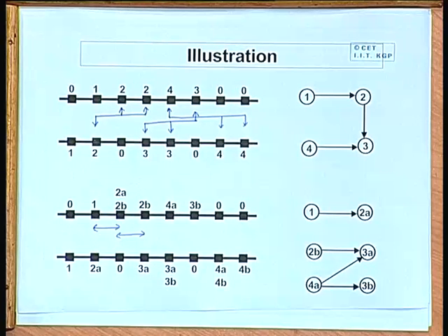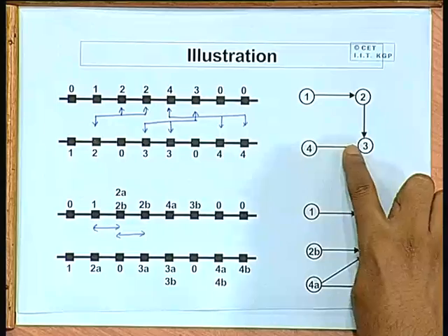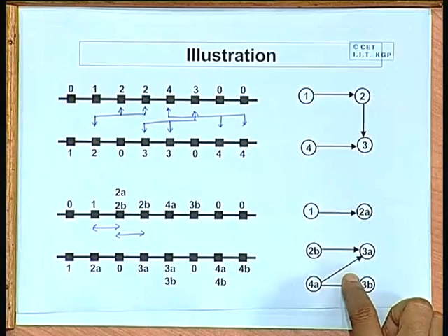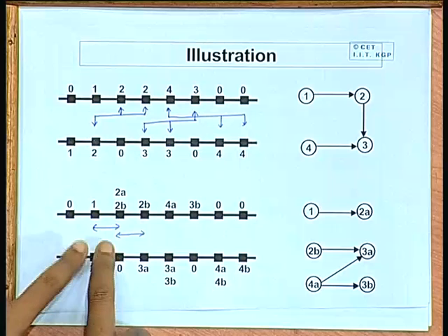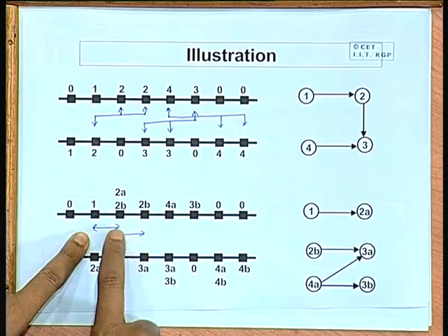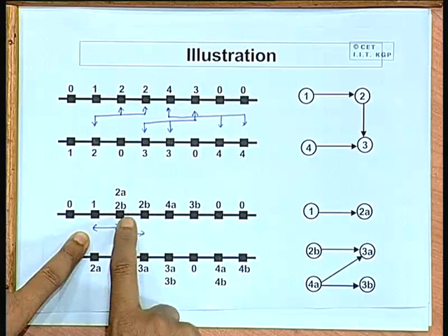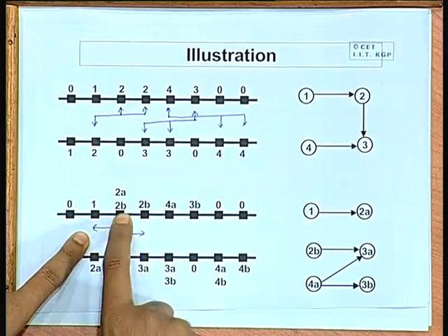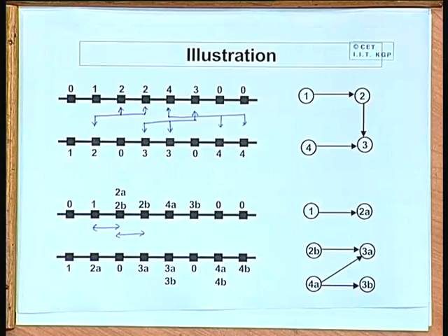That is the idea. But here, although I have not shown the horizontal constraint graph, normally if 2 nets are like this, which start and end at a particular column position, there will be a horizontal constraint between them, they cannot be put on the same track. But since 2A and 2B actually belong to the same net, there will be no horizontal constraint between 2A and 2B. That is the only one change you make in the HCG.